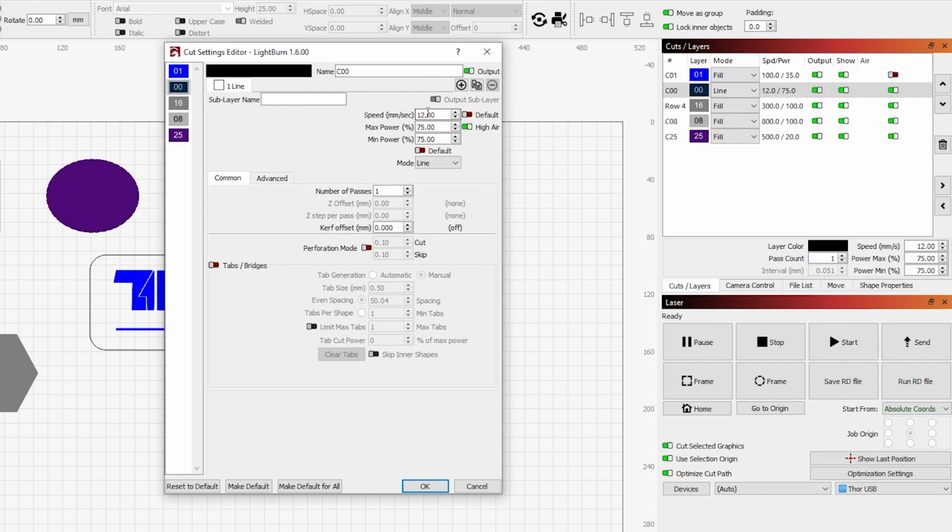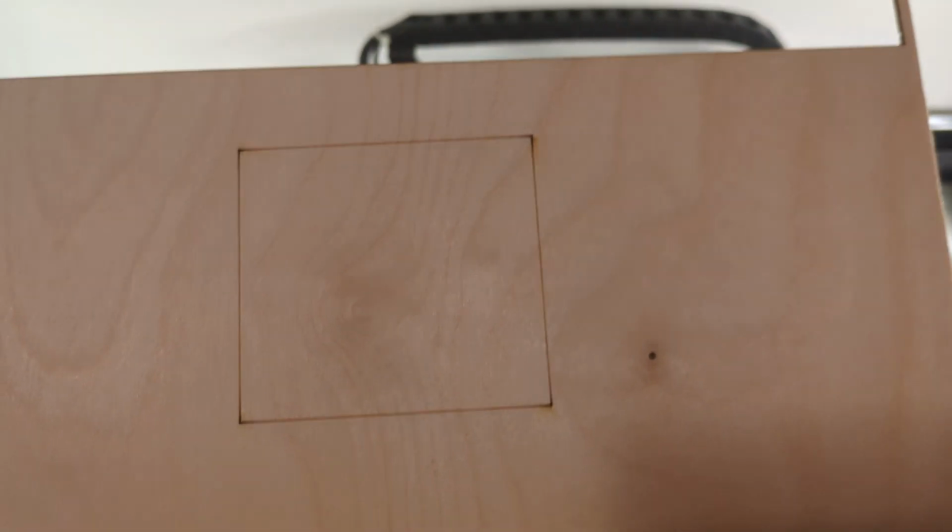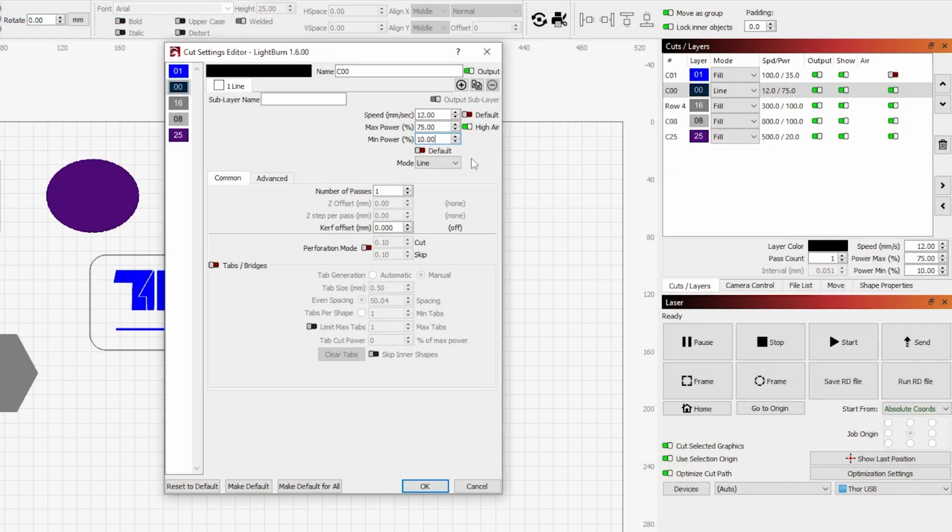Max power refers to the maximum power your laser will cut at, which is the main number you want. But the option for min power will be used by your laser during a cut when the machine slows down to reverse direction, or make a sharp corner. This prevents blown out corners and poor quality cuts on these edges. Normally, you should set this number to just above the threshold where your laser fires. You should only set it at the same as the max power when doing an engrave.